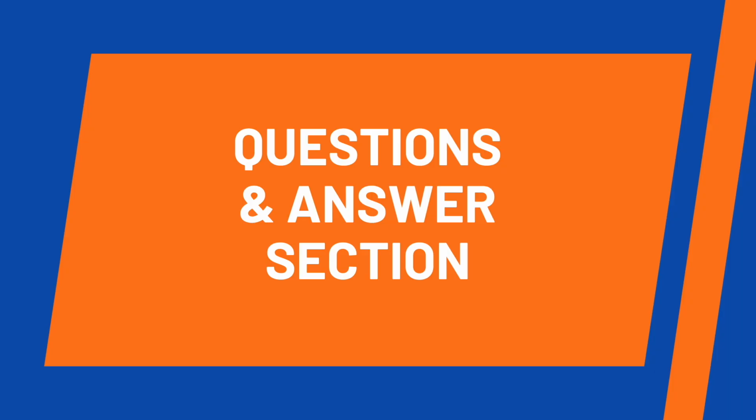When you start getting into building code and stuff, there are other regulatory bodies out there, but my takeaway from what I could find online was basically if you're controlling and mitigating the combustible dust risk to the extent that you can say that it's safe, then you should be able to avoid the H2 occupancy classification. So I hope that answers the question. If not, whoever submitted that, if they want to send an email or set up a follow-up, we can explore that further and get a good answer for them.